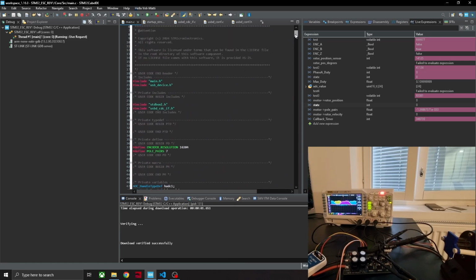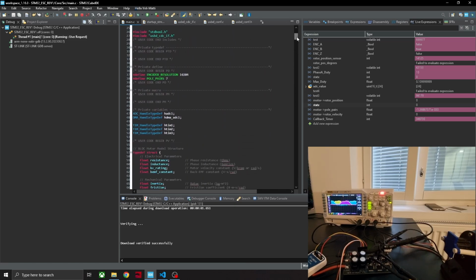Another problem was that the SWDIO I was using for debugging is not fast enough and it is losing a lot of samples. I'm getting 24,000 samples per second on every channel and STMonitor is capable of showing only 1000, so it was missing a lot of details.